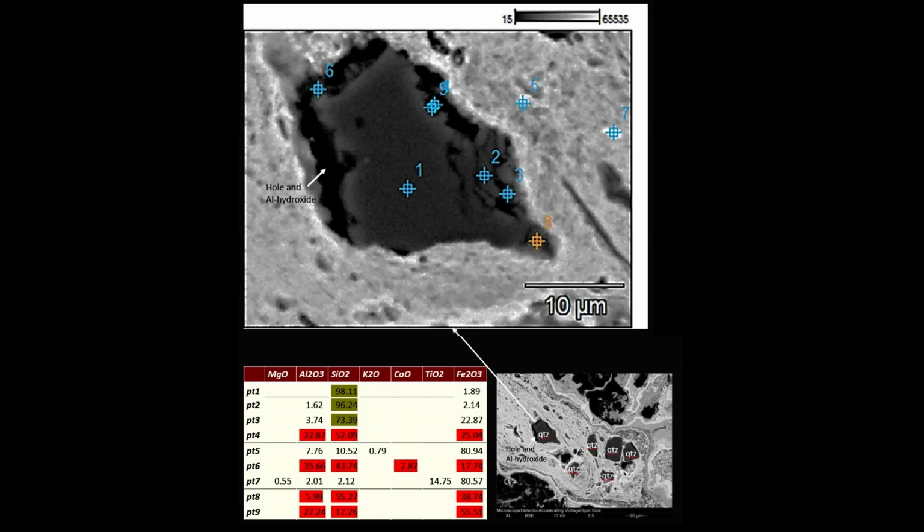A SEM, EDX image of a quartz grain in the bloated area, partly melted by conduction, leaving gaps to the surrounding iron-aluminum matrix. In the gaps, secondary crystal growth containing aluminum, iron, and calcium is not visible here, but can be seen in epifluorescence light images next.